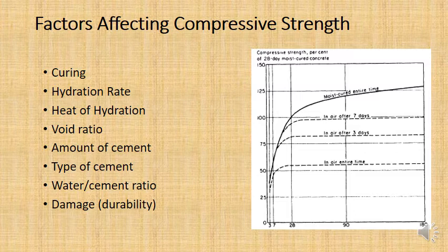You will need about 350 grams of water for the hydraulic reaction in Portland cement. However, in reality, you need more water than that, so you have workability, so you have some slump, so you can place and mix the concrete and transport it through pipelines.